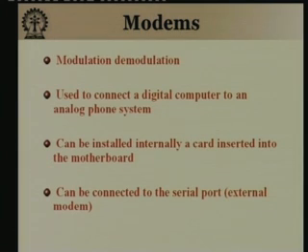And finally, I have already mentioned this earlier, that when carrying digital data over analog lines, we require modems. Okay. Modem stands for modulation and demodulation. This is used to connect a digital computer to an analog phone system usually, okay, but modems can also be used elsewhere, can be installed internally or a card inserted into the motherboard, or can be connected to the serial port, etc. So, now we understand why modems are required, because essentially digital data will have to be carried on the analog system.